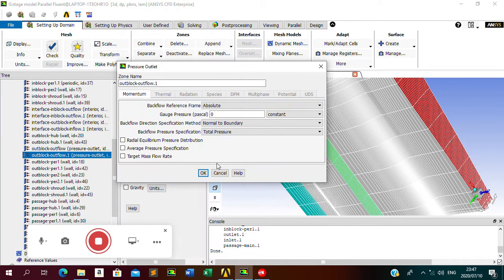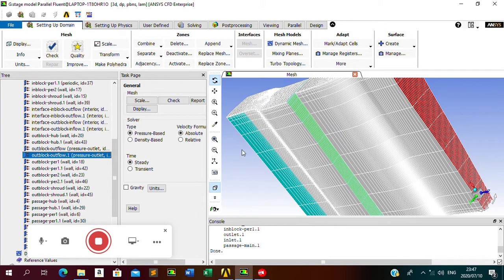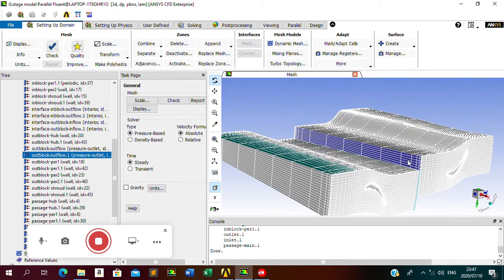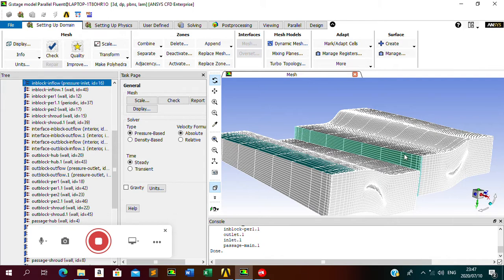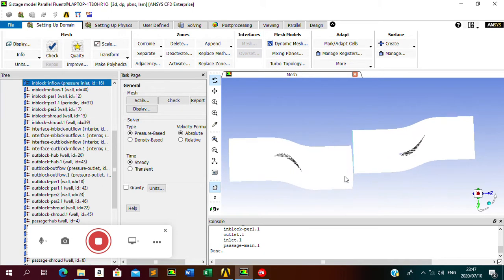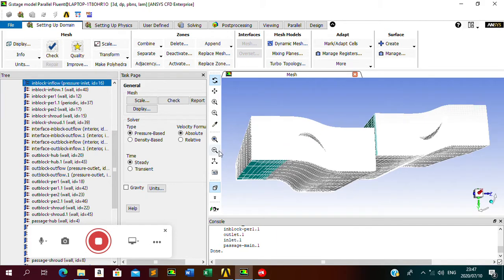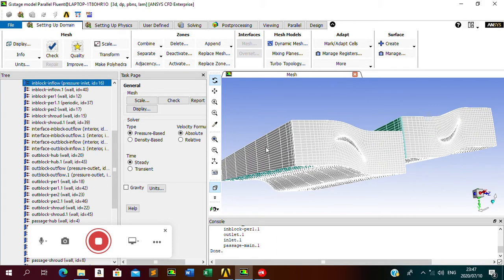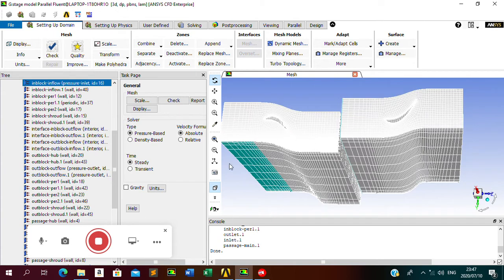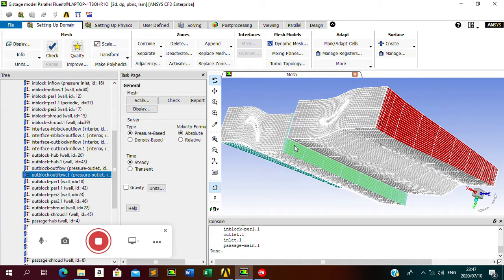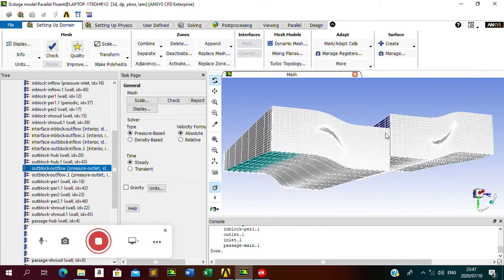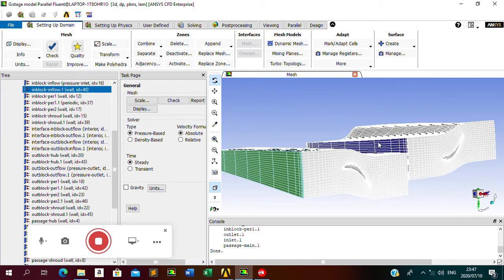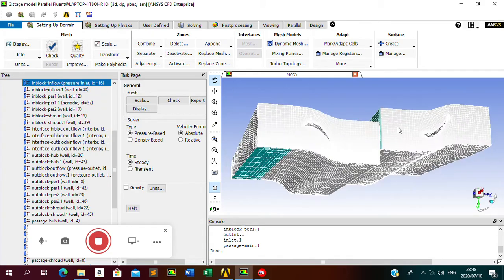I put in the boundary conditions. There's no need to put the boundary conditions because once you link them together, that thing is really just to link these two things. Data will be flowing pretty much. Flow will come from here and then leave here. So this will be your outlet and this will be your inlet. These are more like interface or intermediary zones. This one says it's a pressure inlet, which is what we want, so that's good.